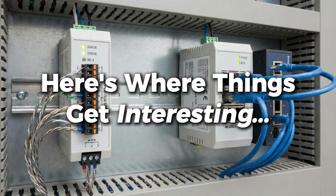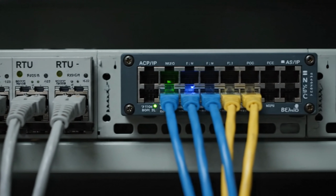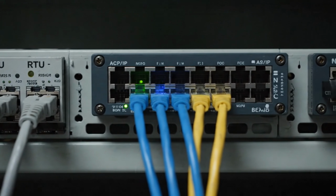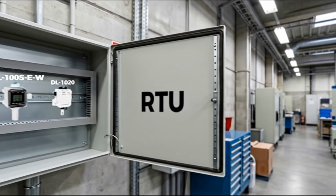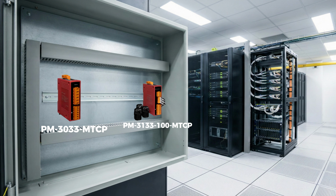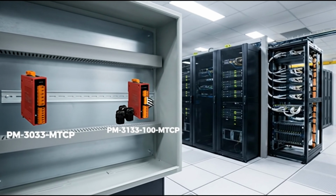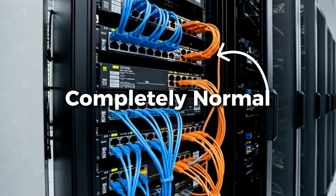Now, here's where things get interesting. In most real systems, you don't get to choose one or the other. You usually end up with both. Maybe your environmental sensors are Modbus RTU, but your supervisory software only communicates over TCP. Or your power meters speak Modbus TCP, but half your field devices are still on serial. That mixed environment is completely normal.